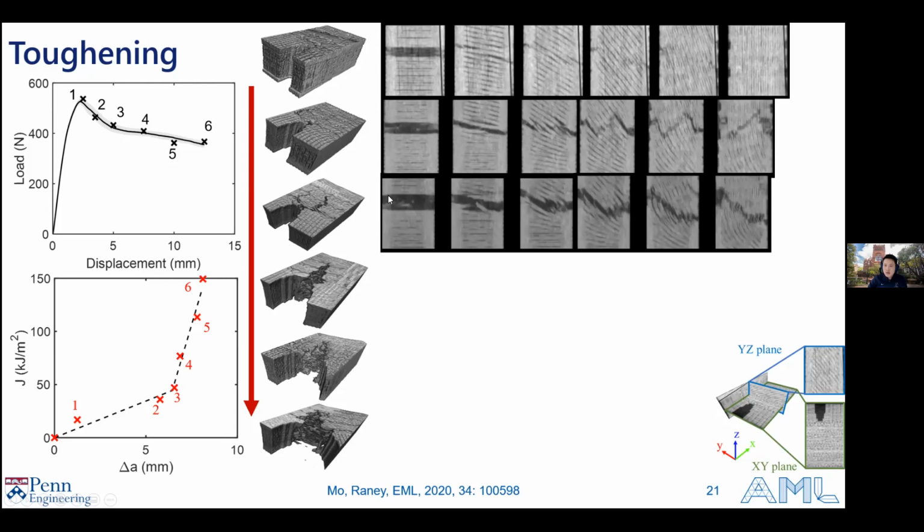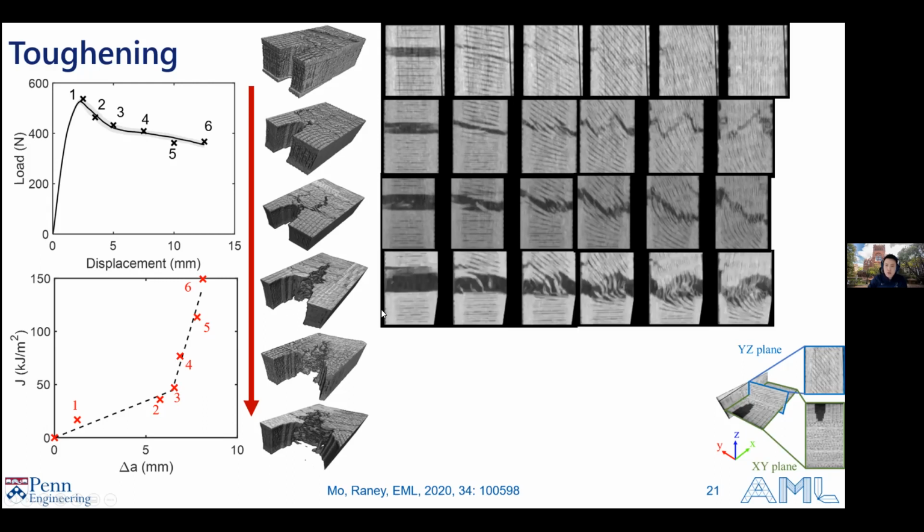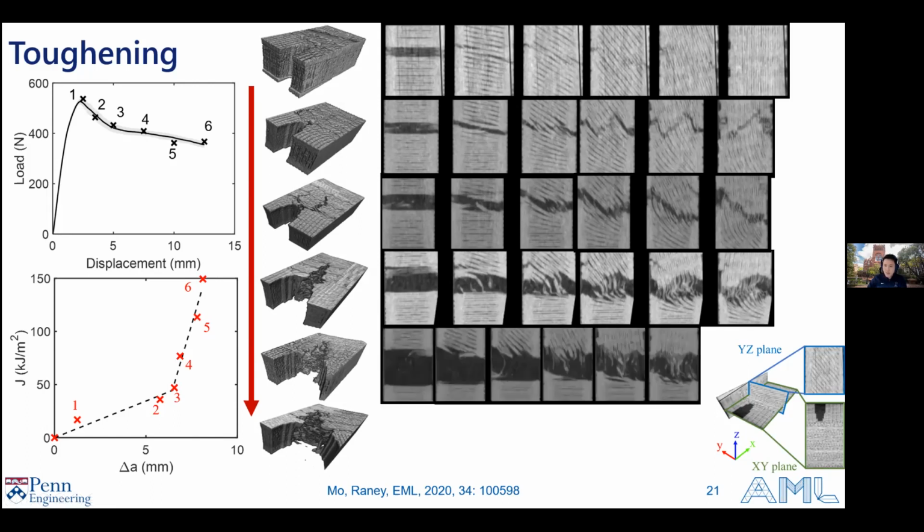However, there's branching, where it's the breaking of the filaments as you go into the center of the structure. And this is also observed in later structures where there's competing factors of fracture in the twisting mode and branching mode. And more so in the later stages, there's actually a change of mode of fracture where you pull these filaments, the filaments become more and more aligned in the loading direction, and you're pulling away these remaining filaments because plastic in general is inherently very stretchable.